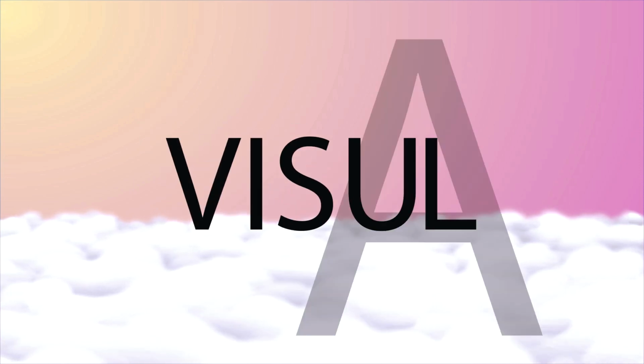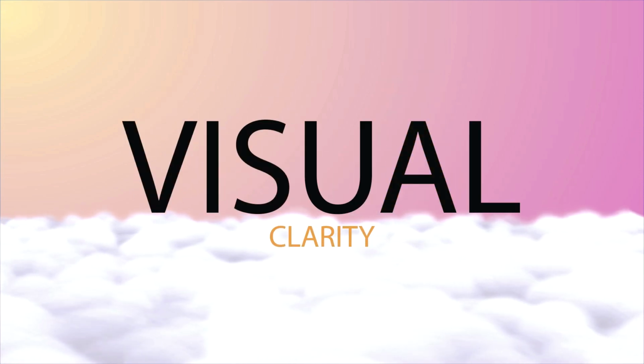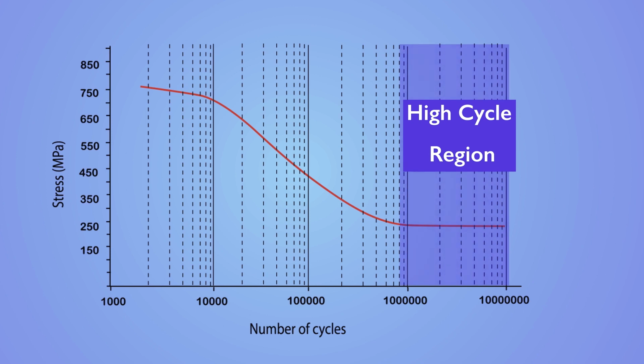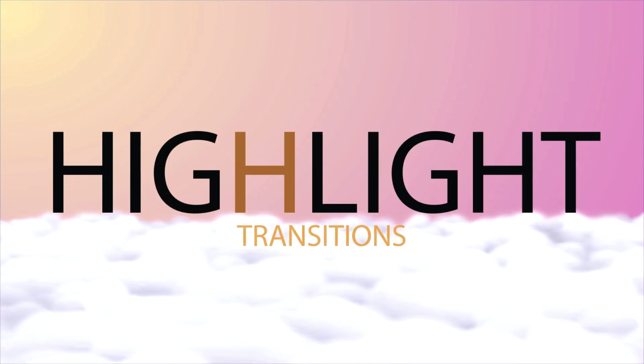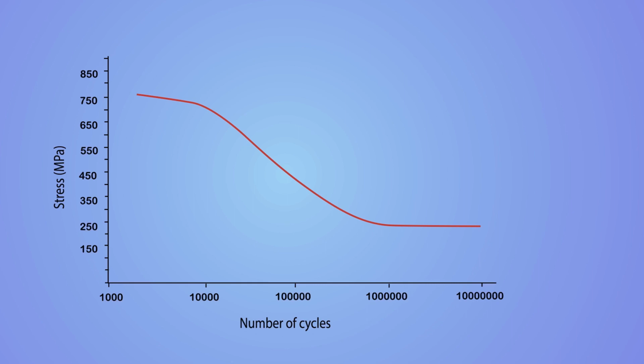Number two, visual clarity. On a linear scale, the high cycle fatigue region, where most engineering components operate, would be compressed into a small portion of the graph. A semi-logarithmic scale spreads out this region, making it easier to interpret and analyze the data. Number three, highlighting the transitions. For some materials, especially ferrous metals, there is a transition from a steep slope to a flatter region. This transition is more evident on a semi-logarithmic scale.